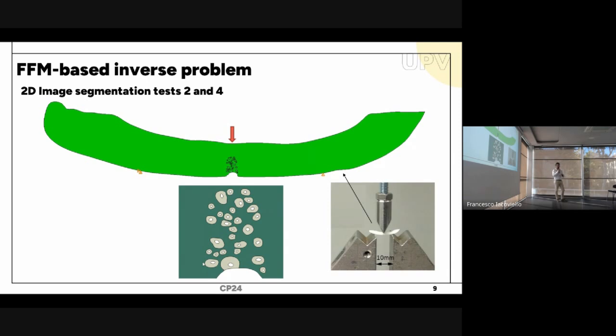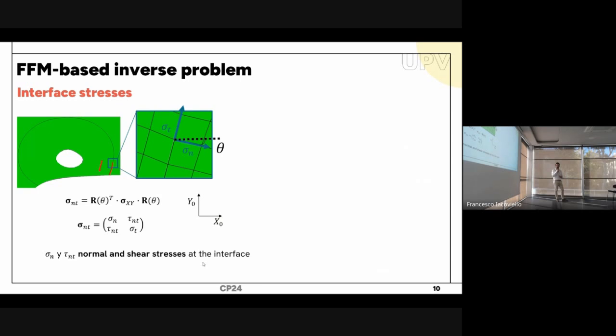I want to emphasize that with this method, we are only going to use linear elastic analysis. We don't need to model any kind of damage yet. That will come later. And the 7 lines that I mentioned are just perfectly bonded here. So now, in order to obtain the stress curve, we just carried out the linear elastic analysis, applying the maximum peak load obtained during experimental testing.